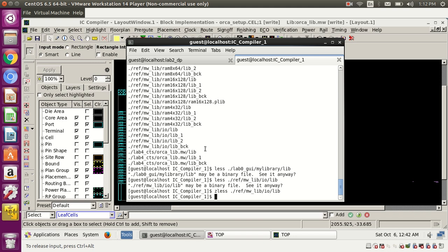But what I am saying is, to debug, suppose in your design there are clock gators. In your timing report we are seeing a clock gating cell. If you see the worst path or some random time-violating paths, you are seeing a clock gator. But the designer said we don't have any clock gating cell. Clock gating may give high delays or unrealistic values. So then only we need to check: this cell is giving this much delay, whether my design should use these cells, or this cell is wrongly placed.